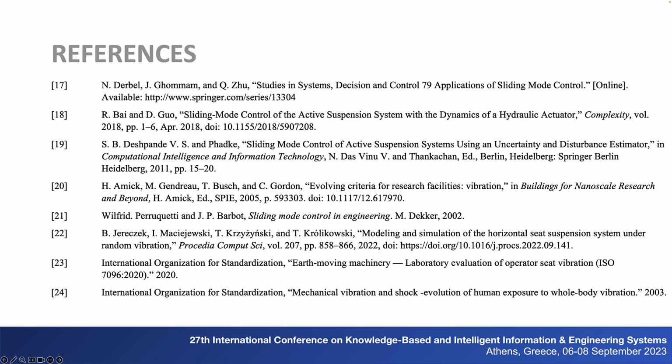It also has a fast convergence rate, ensuring the system's stability and reducing the settling time. This feature is particularly advantageous in horizontal seat suspension systems, as it improves passenger comfort. One of the main drawbacks of the SMC is chattering, a high-frequency oscillation that occurs when the system switches between two sliding surfaces. Chattering can cause mechanical wear and noise in the system, reducing passenger comfort.